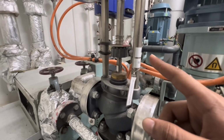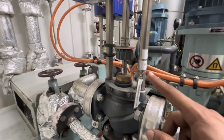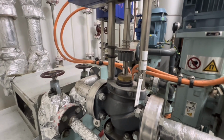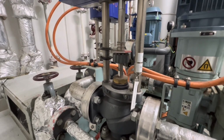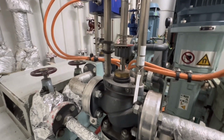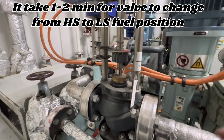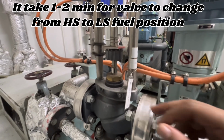Now slowly it will change from heavy fuel oil to the low sulfur position. The timing to change over is already pre-decided by the manufacturer Alfa Laval. So it takes 1 to 2 minutes for the complete changeover from high sulfur to low sulfur.